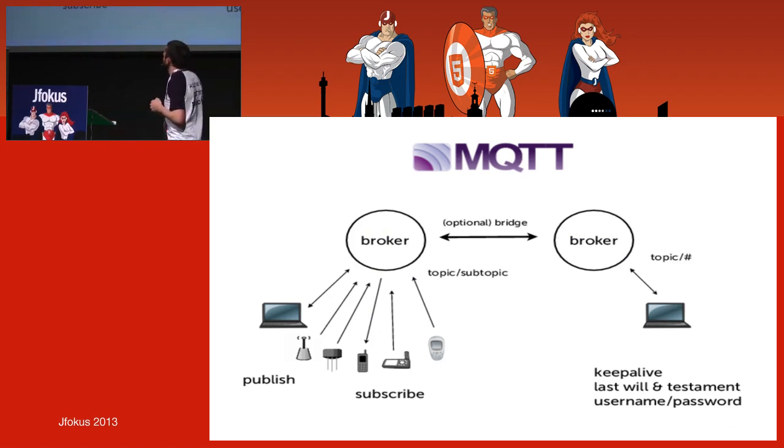So you would have a central broker and several clients, PCs, sensors, embedded devices of any kind that will publish or subscribe on specific topics, with payloads, binary data corresponding to the values you get from the sensors or the commands you want to send to the actuators. So this is the idea.